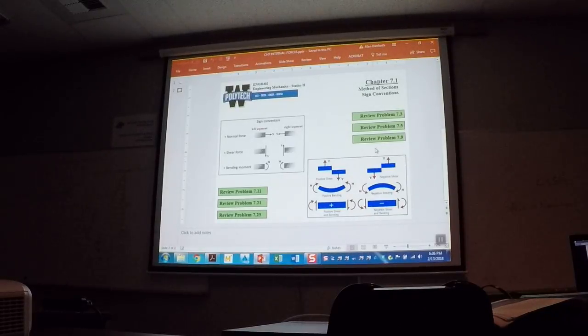And we as engineers can take a very complex thing like a building or a bridge, and with some experience, it might take 20 years, you'll look at it and be able to say, this and this member are the most important ones. I'm going to do a method of sections through them, figure them out, and make sure they're sized properly. That is using engineering judgment to find the critical points in a structure.